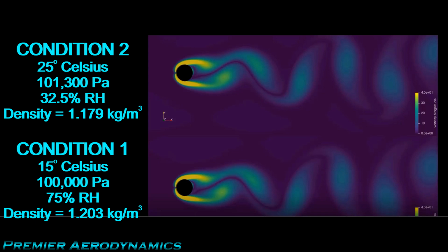Very nice. So if you were to measure 135 pascals in your wind tunnel due to the dynamic pressure, the velocity that you get would be pretty close to what you want. It would be 14.98 meters per second. There is obviously a slight error in there, but it's pretty close. That's for condition one. Condition one, I should mention, is ideal. I picked that because it's ideal. Condition two is not ideal.